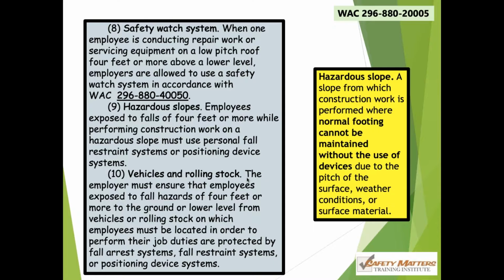And when it comes to those fall arrest systems, what are we talking about? Seriously, I'm on the back of a truck bed. Well, if it's feasible, we're going to have to protect now above 4 feet. If it's feasible, where suitable anchorages cannot be provided, or when the use of fall protection creates a greater hazard, work may be performed on vehicles or rolling stock without a fall protection system. So this is really where feasibility comes in. It has to be feasible.